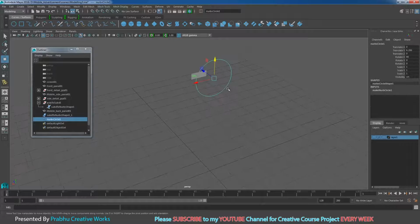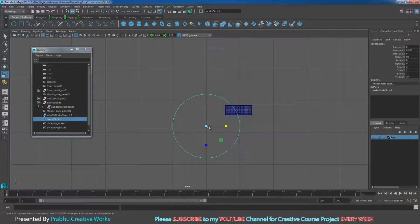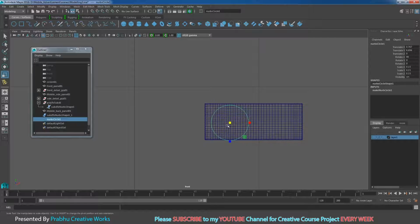So press W and move in Y. So go to front view, press 4 on the keyboard, so press R and scale in the middle, press W, you want to keep it over here, and press R on the keyboard, you want to scale in the middle, press W, I will move it inside. So I want the camera slot here, so press Ctrl D and move this one to this side. So press R and scale this one small. So this is our lens part.